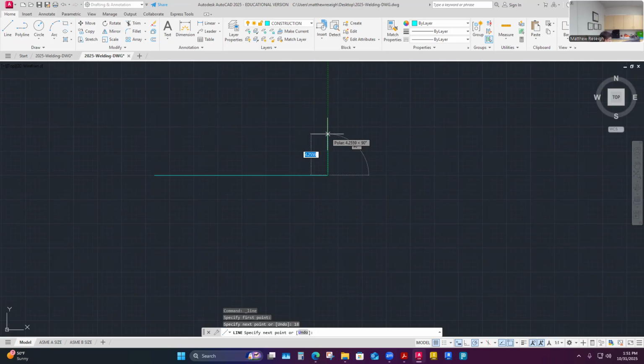So the 10 keypad does a lot of good to have my hand on. It has a delete key on it too. It just has generally what I need with my left hand to input data from the keyboard, and I do my drawing with my other hand on the mouse here. Line is a continuous command. It knows I probably want to build geometry more than just a line. So once you snap a line, when you enter, or if you're just clicking 2 points to establish a line, it's going to keep allowing you to click points as you go around.